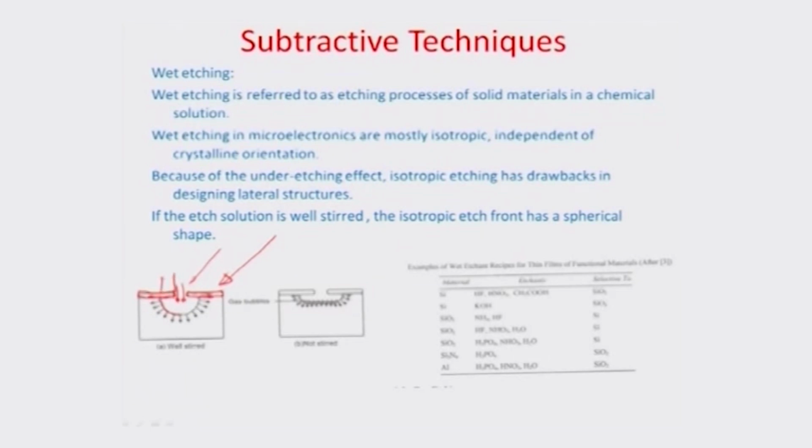So, let us say if this distance is x, this is also known as the undercut, because this was not really intended, it was not planned, and because of the homogeneity the etching would happen in the lateral as well as the vertical direction, which would always result in this kind of an undercut. So, when you design microsystems and the masks for the microsystems, this undercut allowance has to be taken into account for the designing to happen.